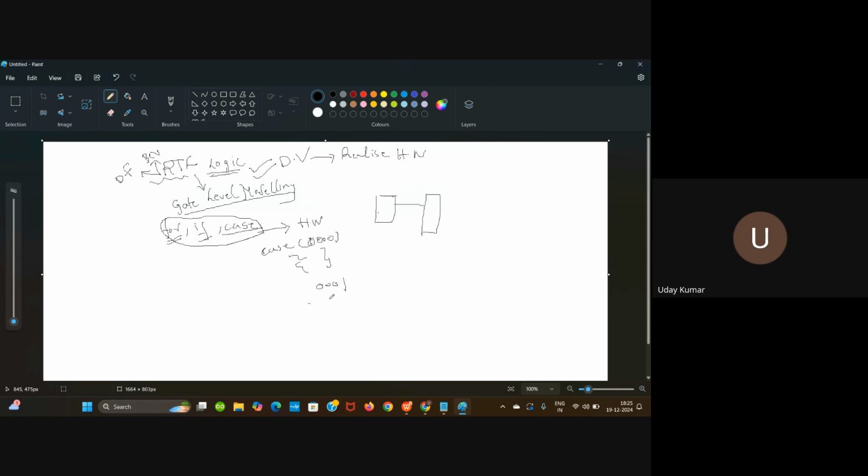And if you consider this as a block, then this block's output will be given to one of the inputs of the mux, and there will be other blocks as well, and you will be having maybe 16, as I gave 4-bit combinations, and you will be having 4 select lines here. So whenever the input is something, the output will be accordingly the same.